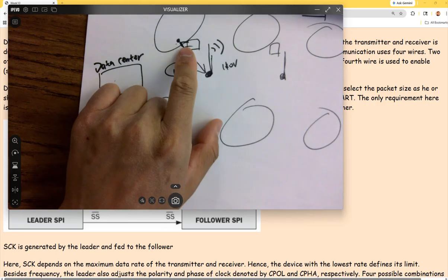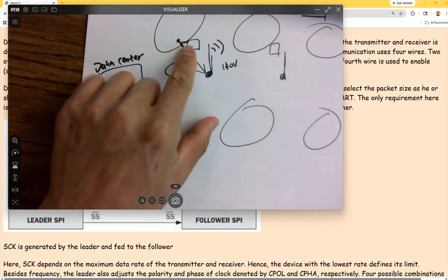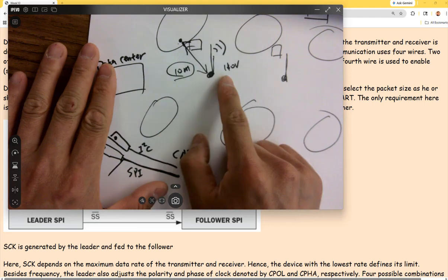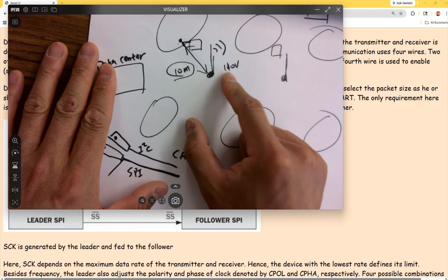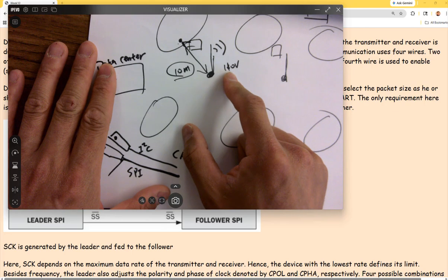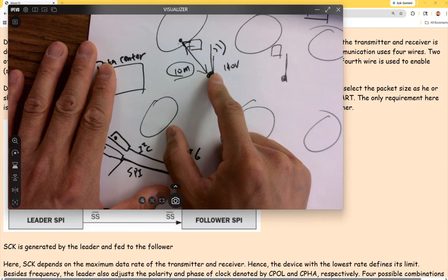And you also need the power. Where does the power come from? Where can I get the power from, just next to the pool? It's not available, right? But for the light poles, you have 110 AC, and you could directly convert it to DC, and then step it down to 5 volts to power up everything over here.